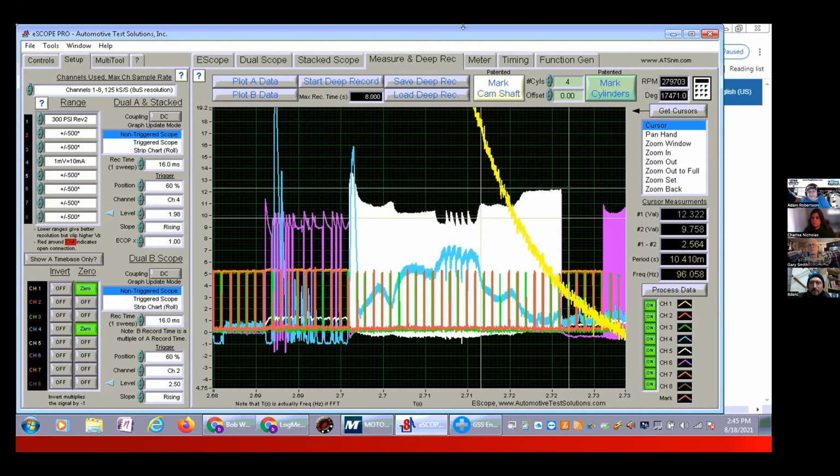It's cool. So just what Adam was saying about the flyback, if you want to quantify that on the screen here, you've got flyback under control. Here you do not. Notice these spikes coming way down when this current is jacking way up. This is your voltage representation of your flyback occurring against the ground of that driver right there. You can see it in physical form right there.